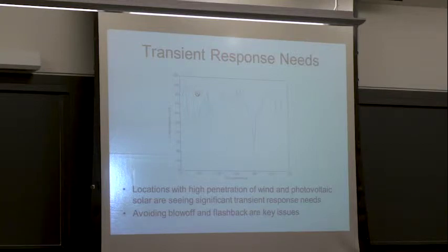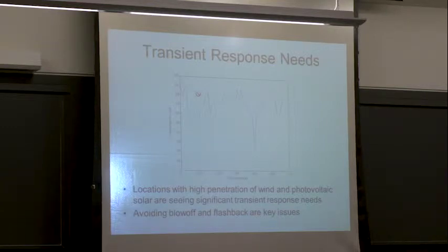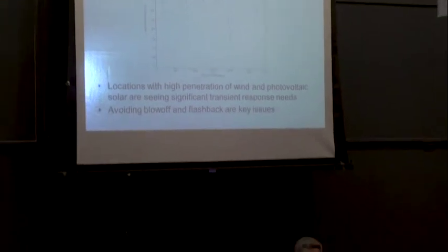So are aeroderivative gas turbines more popular because they can be turned down quite a bit, right? Yeah, so you'll see lots of things. You'll see aeroderivatives, but even simple cycles are being popped all over the place. And it just depends on time scale. But aeroderivatives do have really fast transient response, and they're oftentimes used for load following.